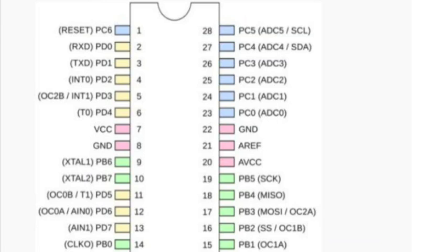And in parentheses, I've written their pin names as they're listed in the data sheet next to the pins, so PB1, PB0, and then in parentheses their main functions. And so that's where the internal hardware peripherals are hooked up. So you can see things like in the upper left-hand corner, pins 2 and 3 are PD0 and PD1, but they're also used as the serial receive and transmit lines, respectively. We'll talk a lot more about this as we go along.